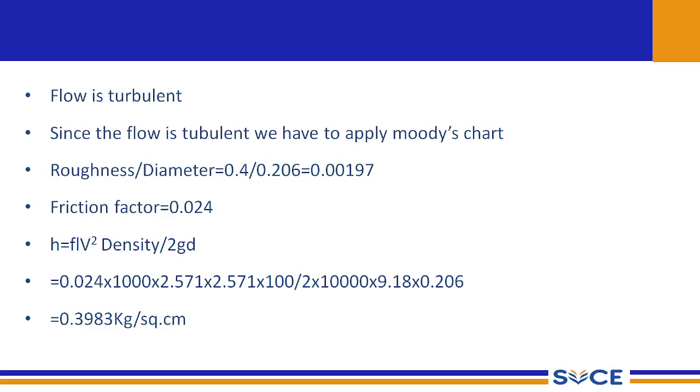we determined. We also have to look at some standard diameters which are close to our calculated value. If our value is close to some standard diameter, then we choose that standard dimension and we estimate the pressure drop based on that diameter of the line.